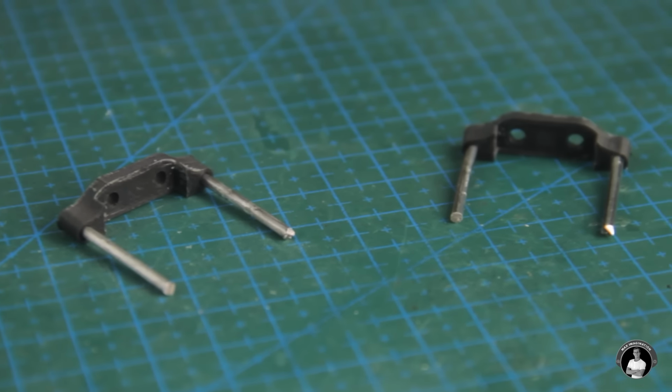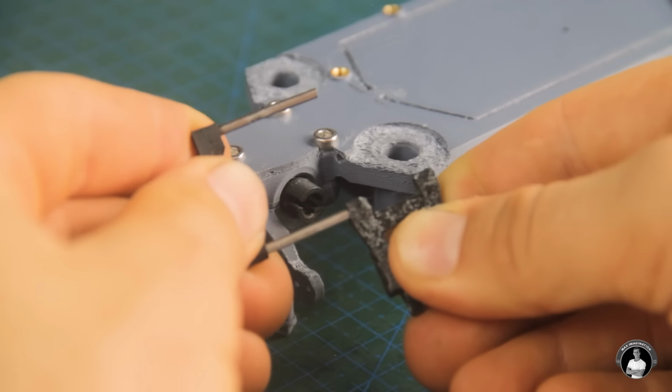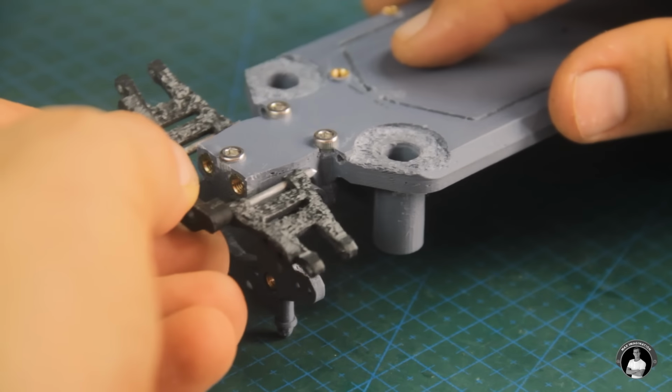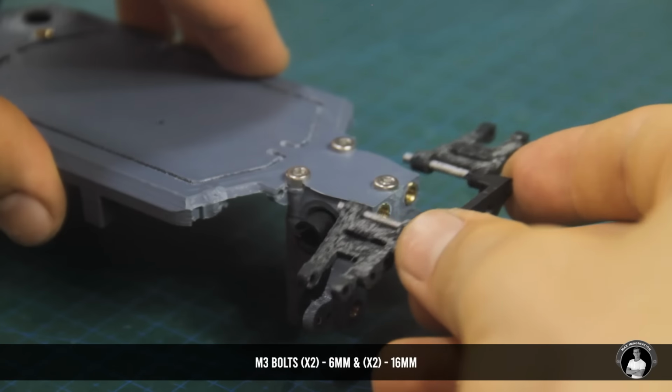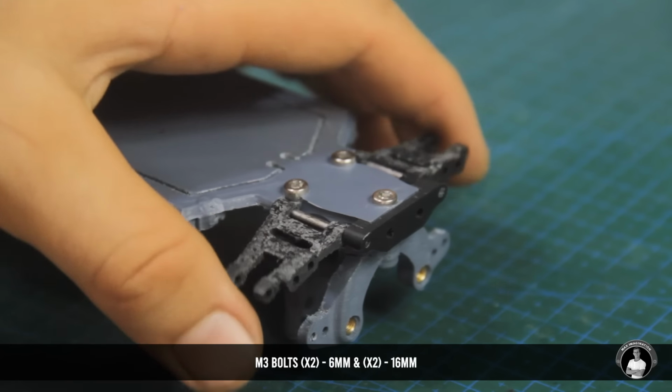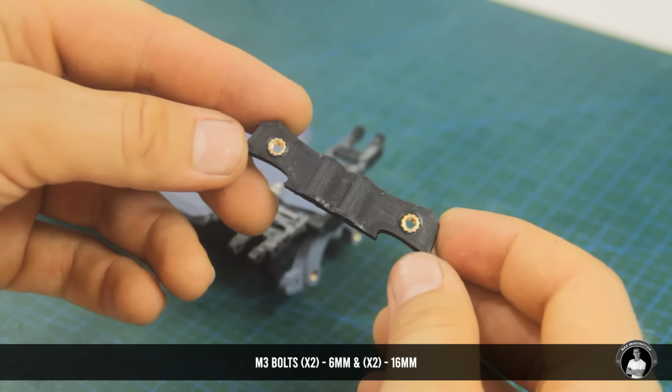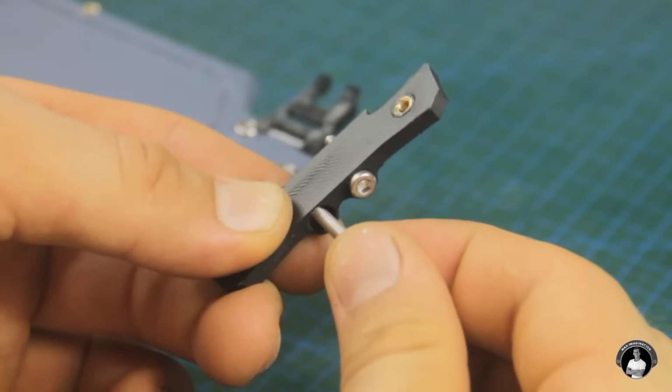With the help of each, the swing arms can slide onto the fork parts and then into the chassis. However, the front fork gets secured with the front bumper holder using the longest bolts in your M3 screws kit. Keep in mind that it actually needs to be installed with the flat side facing up.